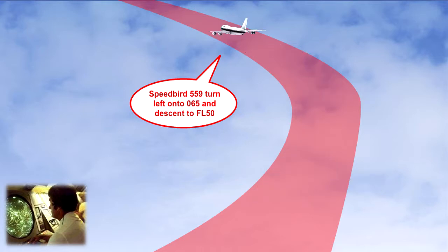There may be occasions when pilots specifically request the controller to provide radar vectors. This might be to avoid bad weather, or the loss of navigational instruments might result in a request for vectors to assist in navigation. In such cases, the pilot must inform the air traffic controller of the reason, be it weather-related or due to unreliable ground navigation equipment.